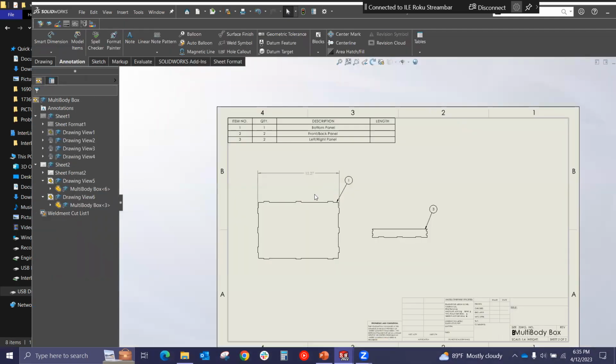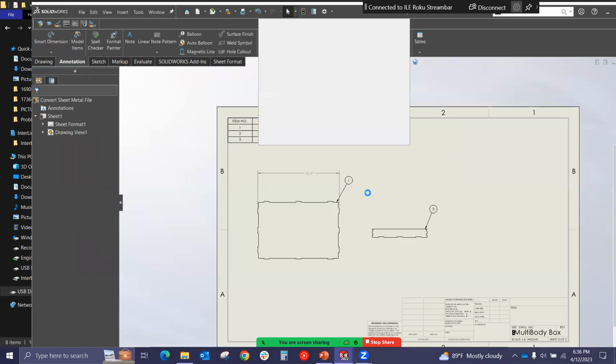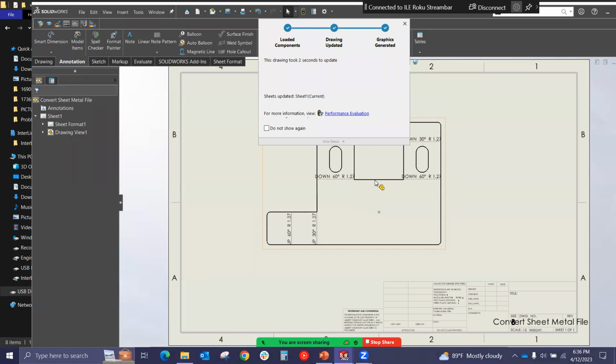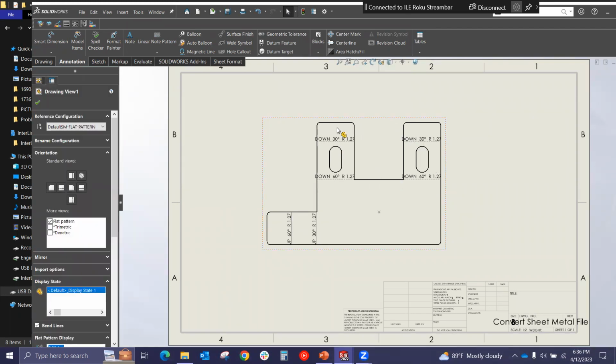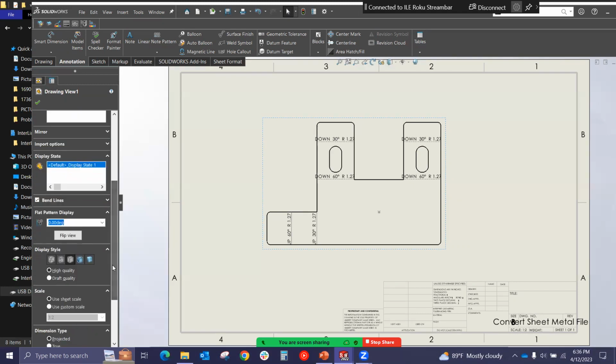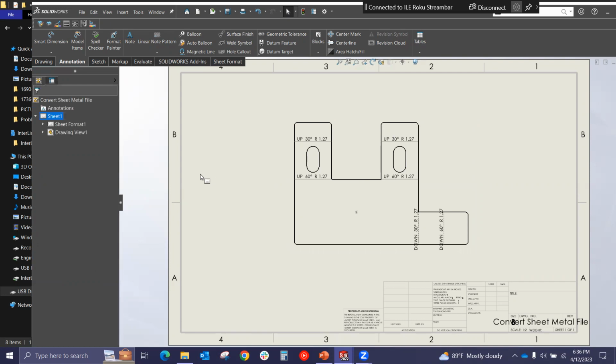Oh, wrong one. This. And then from here, you'd be able to change it so that if you ran that macro, it'd pull this flat pattern as opposed to this showing as up, but your DXF exporting for something that needs to go down, which can scrap a bunch of parts if you're running, you know, overnight or something.